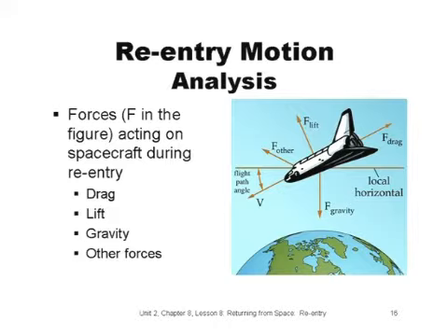Okay, keep following the diagram and let's go back again to the motion analysis process. One of the steps is to make a complicated equation easier by thinking of some simplifying assumptions. First, we assume that the re-entry vehicle is a point mass instead of a complicated aerospace vehicle. Then we say drag is the main force, which means that all other forces, including lift and gravity, are insignificant. And we'll see why this assumption is good later. Lift is a force at a right angle to the direction of motion as a result of air moving over an object's surface. The motion analysis approach for re-entry vehicles requires us to develop an equation of motion and examine how different parameters affect it.